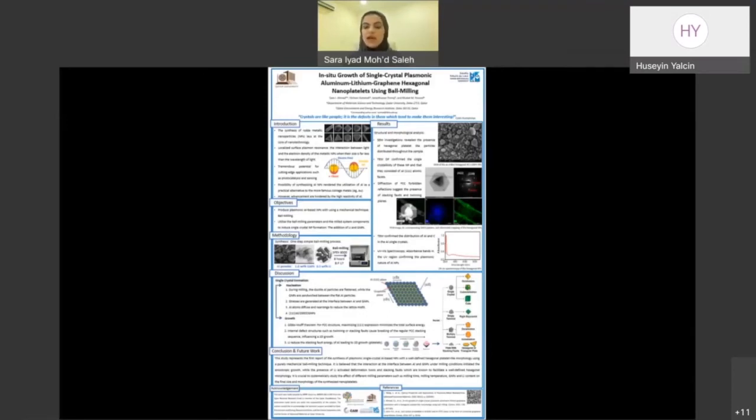Now, the growth of the hexagonal nanoplatelets is then supported by the context of the Gibbs-Wulff theorem, which suggests that for an FCC nanoparticle, you need to maximize the 111 planes in order to reduce the total surface energy. And so you end up with a three-dimensional tetrahedral or octahedral nanoparticle. However, even though our TEM investigations prove that our hexagonal nanoplatelets have 111 facets, they are rather two-dimensional and hexagonal in shape rather than three-dimensional and tetrahedral or octahedral in shape.